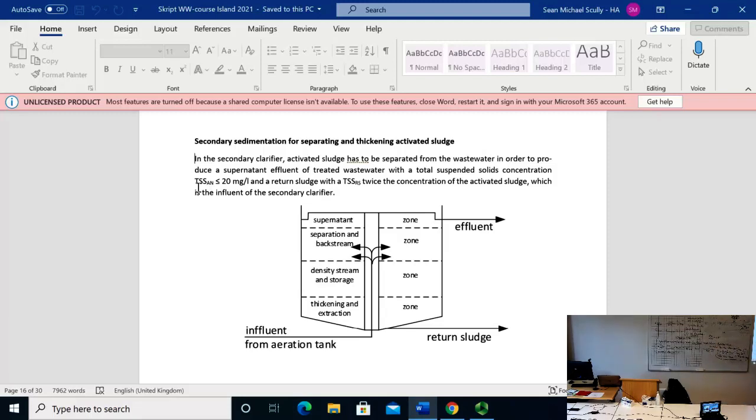Now, what more do we need to calculate? Well, we want to have the diameter of the tank. Also, we have learned that the superficial area is important. Well, basically, we have learned from our experiment that we determined this by the residence time more than anything else, because we took half an hour and then we measured the sludge volume index.